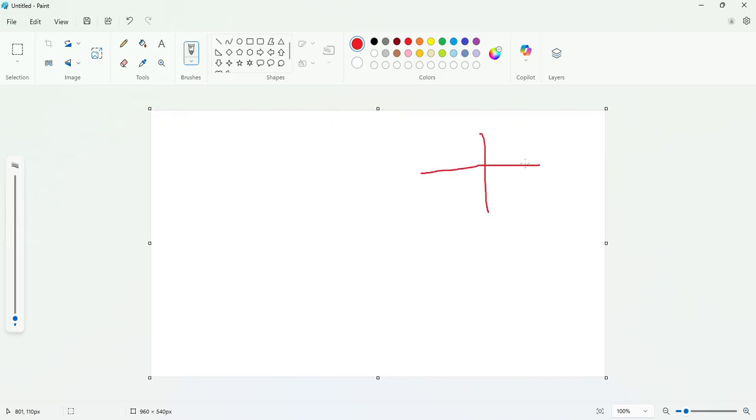this was our quadrant. The point was here, A, which is 20 mm above HP and 30 mm in front of VP. To the right side of VP is in front, and to the left side it is behind. So this point is in the first quadrant. Point A is in the first quadrant, 20 mm above HP and 30 mm in front of VP.